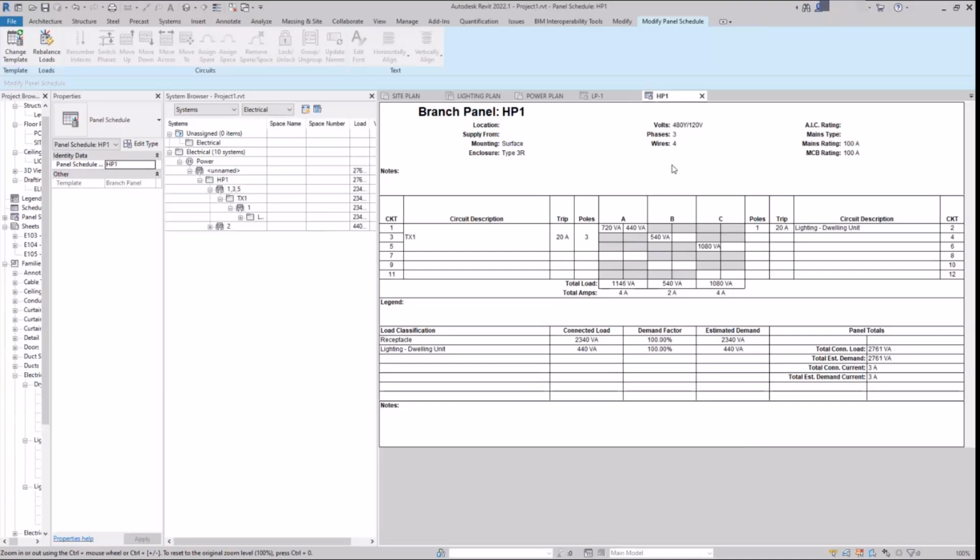Meaning, if you could theoretically put 50 lights on a single breaker, but that covers 5 different rooms, okay, they're like massive rooms. I'm thinking a specific case where we did a courthouse. The lights were nothing. Like we hardly put any power on the lights, and we literally could have done about 5,000 square feet on a single breaker, but it just didn't make sense. Like if that breaker trips, the entire floor goes down. The entire building's SOL. Yeah, exactly.